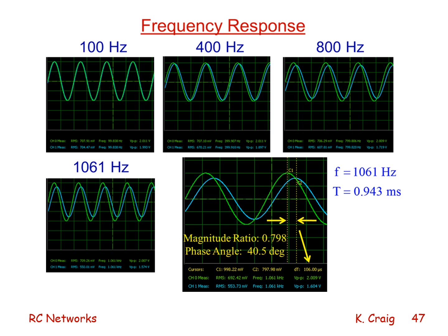Now, what does this Bode plot physically mean? Well, what it shows me is that if I input a sine wave at a certain frequency, I get a sine wave out, same frequency, but as I increase the frequency, the amplitude ratio will get smaller, and the phase angle will go from 0 degrees to minus 90 degrees. So I see at 100 hertz, the two sine waves are almost identical.